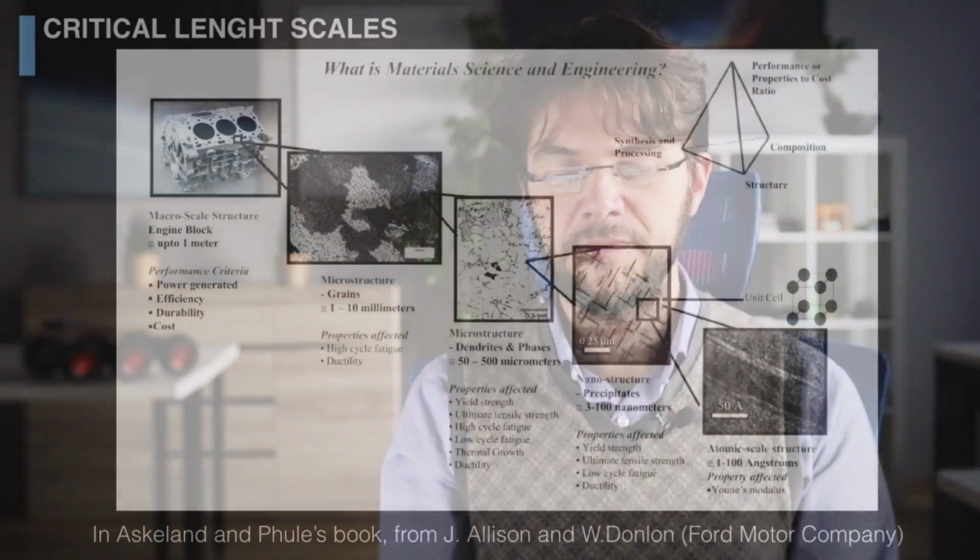The transformers have an iron steel, silicon steel core that is grain oriented in order to have better permeability of the magnetic flux line according to a certain direction. So the working process allows you to orient the grains and recrystallize a little bit the material in such a way that you will find mostly grains which have the same anisotropy axis.